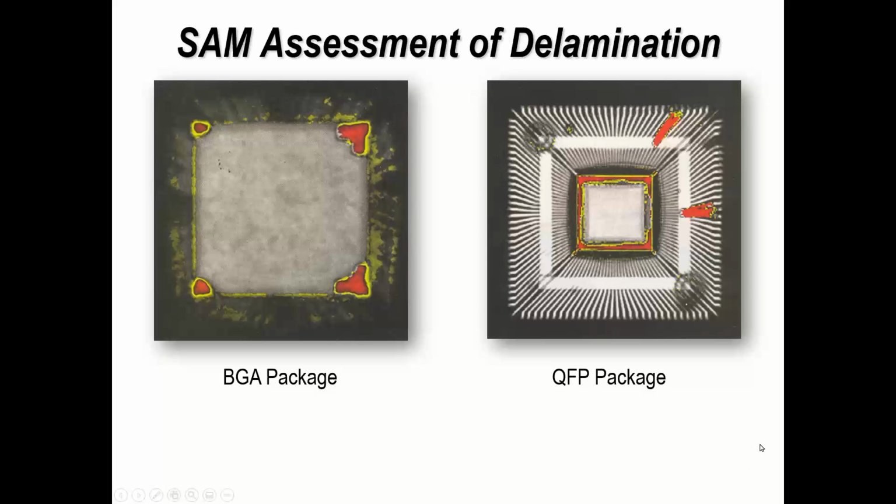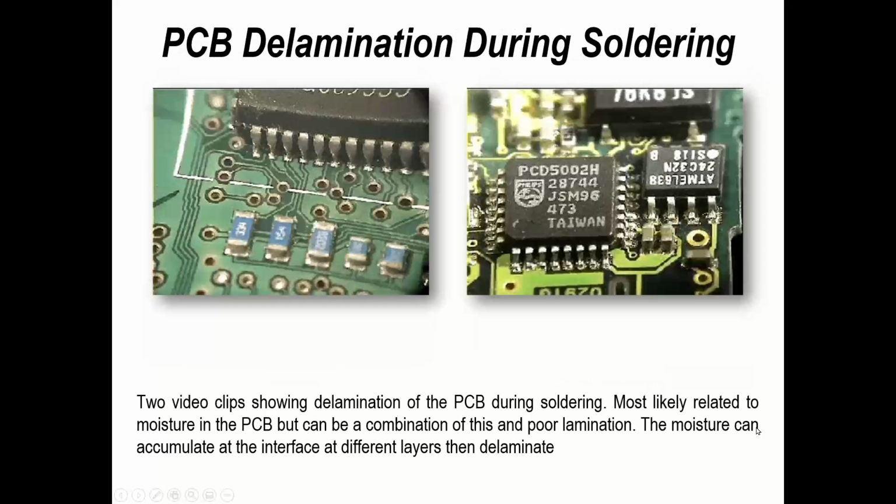Normally you wouldn't take it off the board, ideally, because if you add the board and have another soldering operation, you may have damaged the part that you're trying to investigate by removing it from the board. So that's why you might see it done on an assembly as opposed to on an individual part. So that's on the component side, what it looks like, how it fails, what potentially can cause it to fail. Let's now look at the printed circuit board.